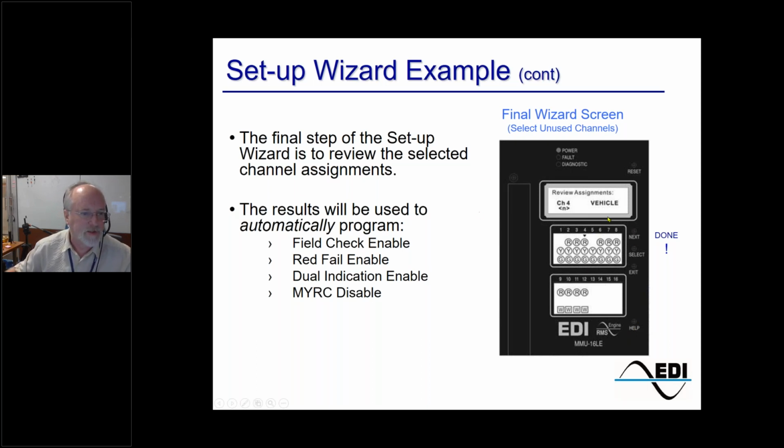Because what that does is it tells the intersection or the monitor that there's going to be pairings, like channel 1's going with 9 yellow, or channel 1's going with 13 green. Is there any question there? Yeah, so then there's 2 setup wizards. If there's no flashing yellow arrows, you can just do the basic setup wizard. Correct. Okay. So do the flashing yellow one first.